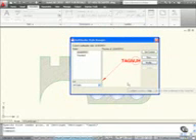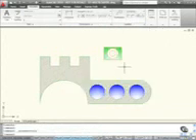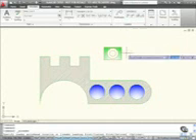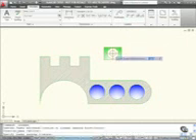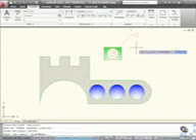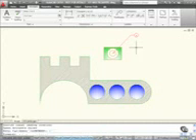So what happens now when I draw a leader using my leader style? Well, let's make leaders 1 the current leader style. So let's set current there and close. And what I'm going to do now is place some leaders. So there's the multi-leader command on the leaders panel. Click on multi-leader. It says specify arrowhead location. Going to use the center snap there. Left click, drag upwards like so, left click again, and there's my leader with my bubble waiting for my tag number. So AutoCAD is now prompting me for a tag number. So if I now put 1 in there, like so, and press enter, there's my bubble with my tag number in it.